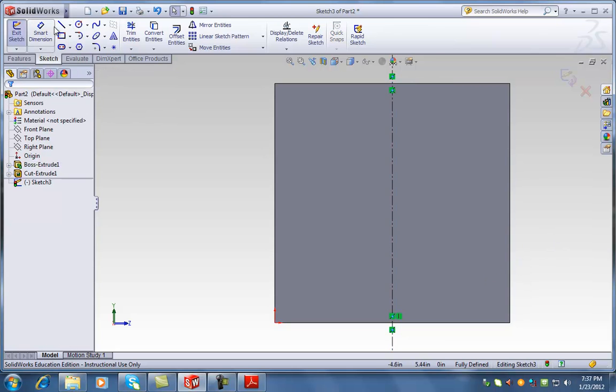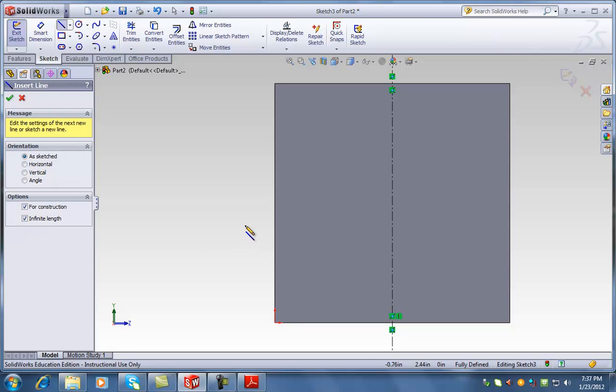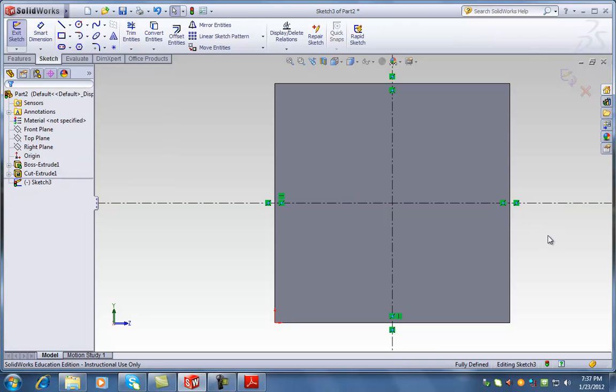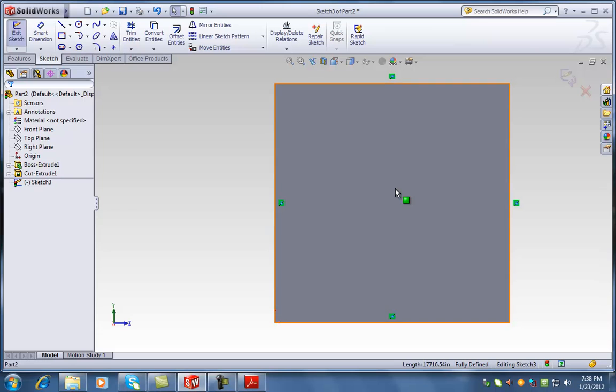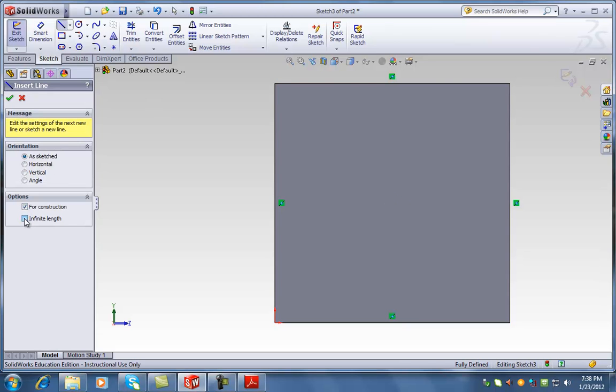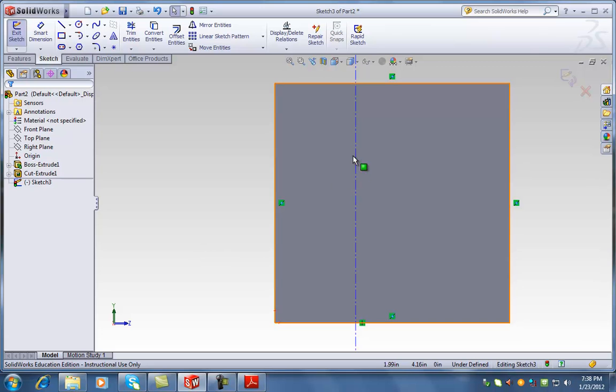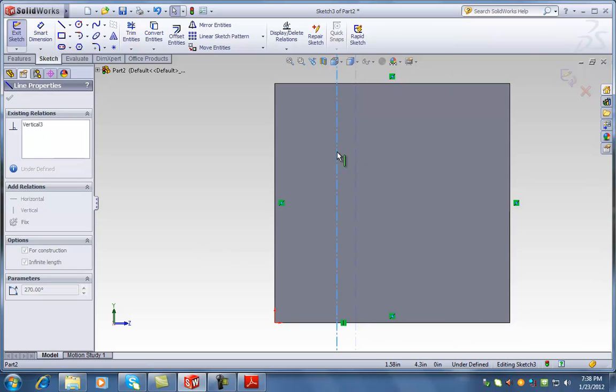Okay, now let's do another one, but let's do an x-axis this time. So again, we're going to start from here, and we're going to do an x-axis. So now we have an x and y construction system. Yes, JD? This line is still blue. How did it get into black? We tried pushing Escape. Good point. Okay, so let's go through these scenarios. Let's say I started my construction line, and I actually did not start it from the midpoint. I started from somewhere here. So this construction line does not really have any reference to anything, so I can grab it and move it around. Is this the problem that you have? Okay. One of the options that you can do, which is my favorite, is to simply delete it and do it again.